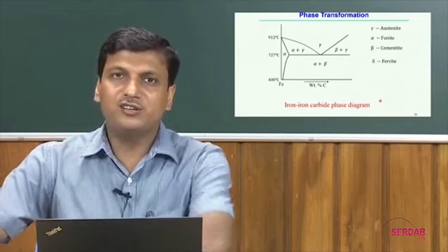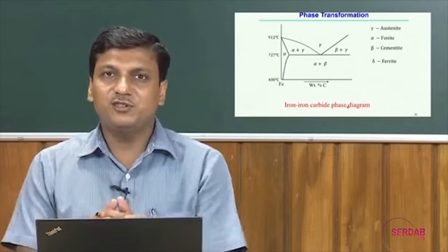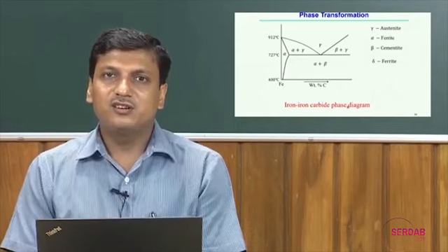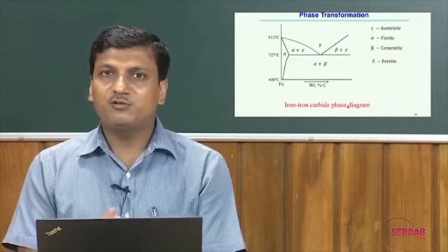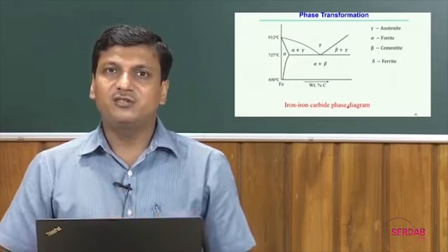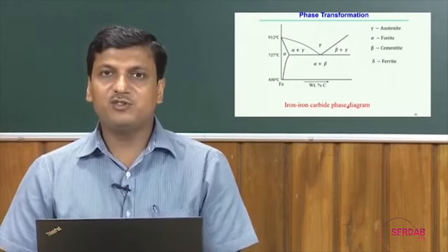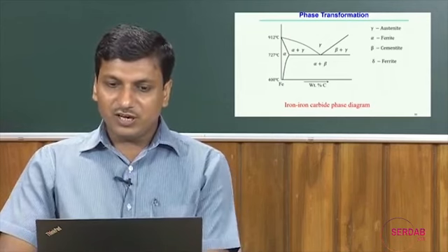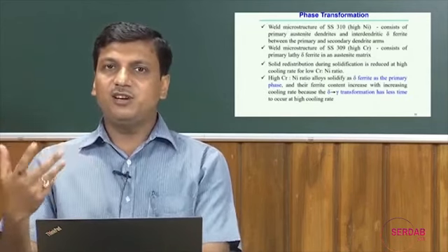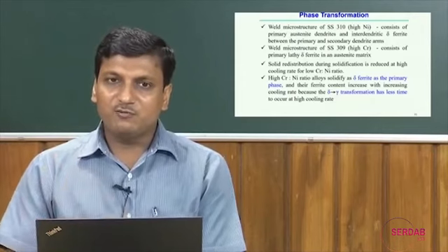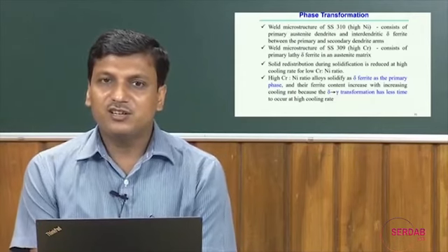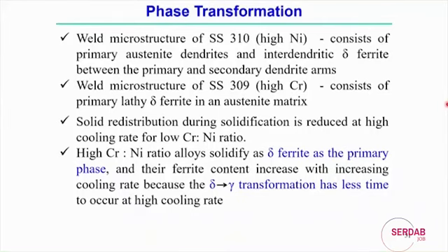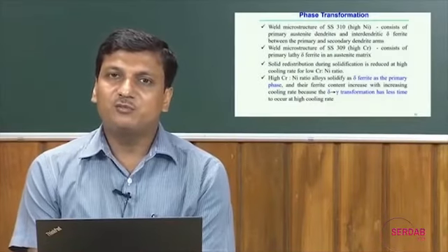If we know the phase mixture, we can use the lever rule to find out the proportion in which the different phases exist within the mixture. That kind of information can be well extracted from the phase diagram. Anyway, if we look into the welded structure, we want to know what phase transformations may happen, and how they can be predicted in the final structure with respect to the type or composition of the material.